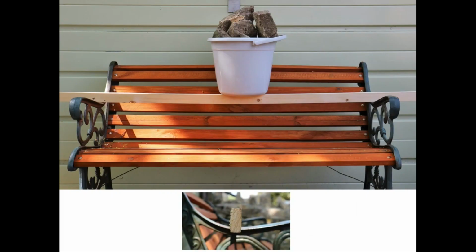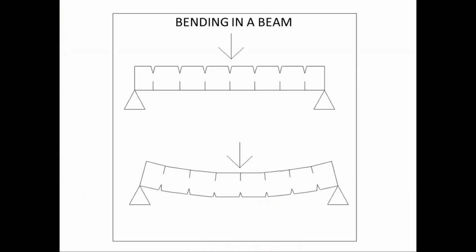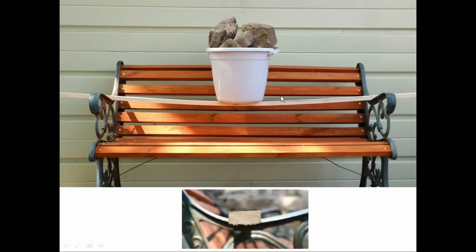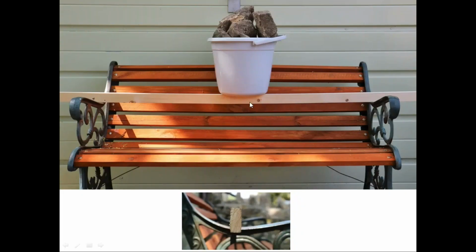So there's a beam that's still slightly bending. So actually, if we didn't want it to bend at all, it would probably have to be slightly deeper than that. Now what's happening in reality here is that the compressive side, the top half of the beam that's in compression, does not want to get in contact with the bottom side of the beam, which is in tension. The moment that happens, as is happening here, the top in compression is very close to the bottom part in tension. The closer they get together, the more likely they are to fail.